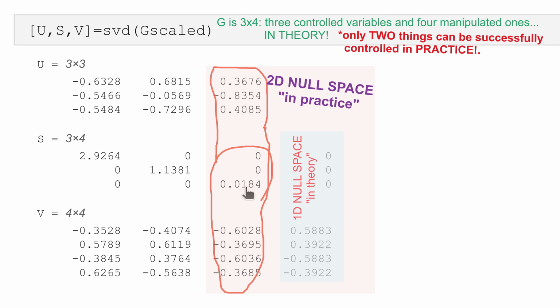Also, as my model has, let's say, 100 times lower signal to noise ratio in identification experiments, my model will also likely be very bad. So bad model quality and low gain will give me saturation and risk of bad performance due to modeling errors.